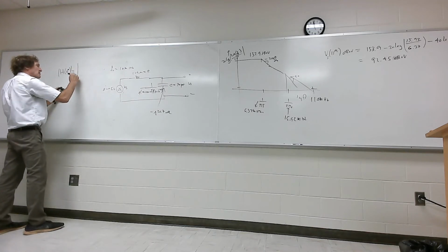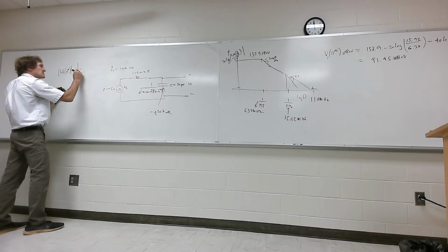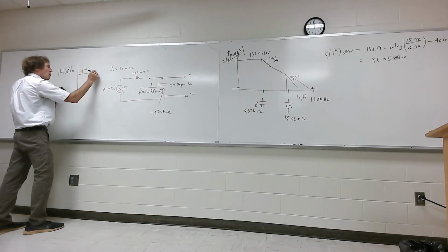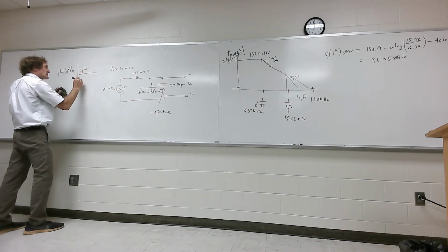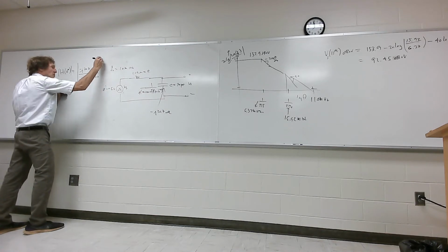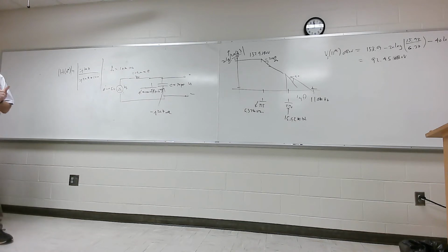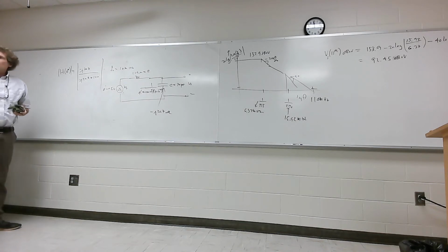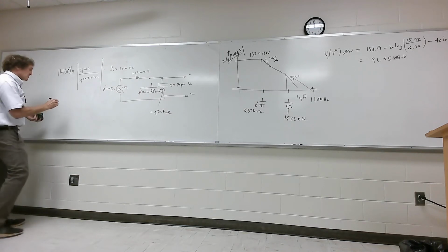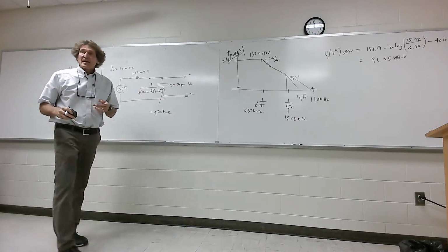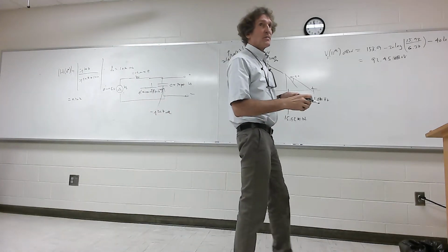I'm just gonna put it down. Magnitude of minus J20.7 over minus J20.7 plus 100 ohms. Y'all follow me? Can you give me the magnitude of that? I think it's 0.29. Could you tell me? 0.202. Y'all get that, guys? Is it 0.2? Yes. Okay. Equals 0.202. Now, we get the value of the output voltage.